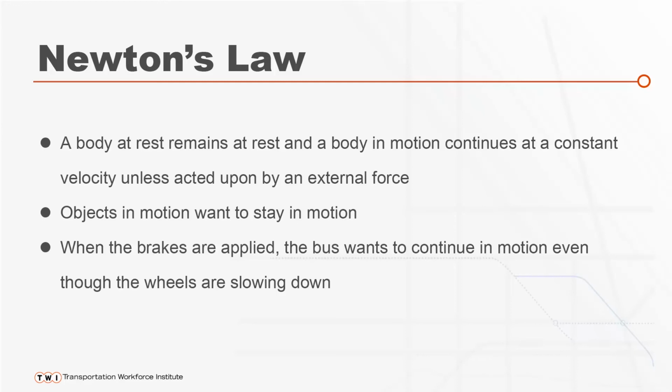So that's where Newton's law comes in: an object in motion wants to remain in motion until an opposite force or the brakes are applied. Always remember, on a long wheelbase vehicle, the primary brakes or the larger brake force is on the rear because we want to pull the vehicle to a stop to keep it in line. On a short wheelbase vehicle, cars, pickup trucks, motorcycles, the weight is transferred to the front fairly rapidly, and because it's so short, we want to apply the front brakes at a greater rate than the rear brakes.